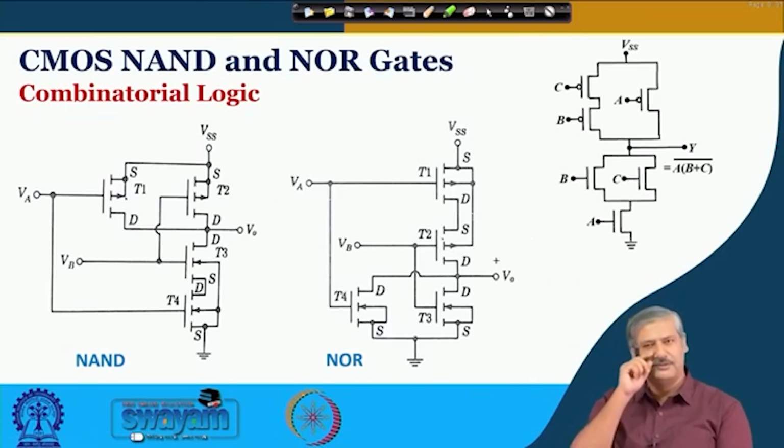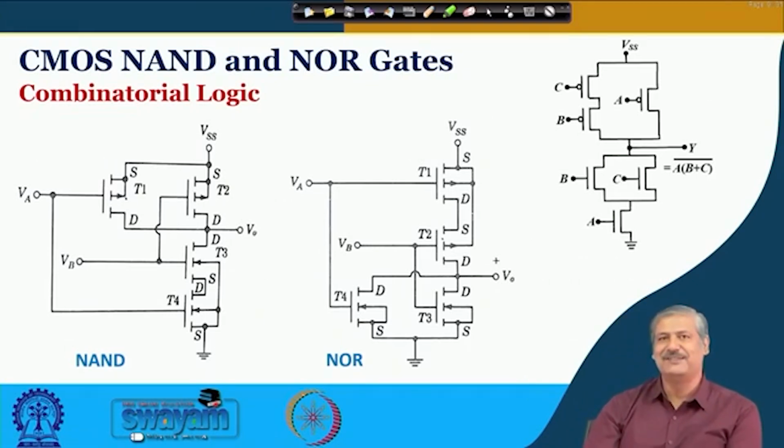Fine. So, we go to this, one beautiful thing about these MOS based gates. Okay. So, when we look at development of NAND gate or NOR gate or combinatorial logic, we do not need resistive elements and other things that were there in BJT based circuit development. So, in NAND gate development in CMOS, we need for every NMOS another corresponding PMOS, okay, to get the advantage of the CMOS circuitry. So, for NAND gate development, we have two NMOS in series and the corresponding PMOSs are in parallel.